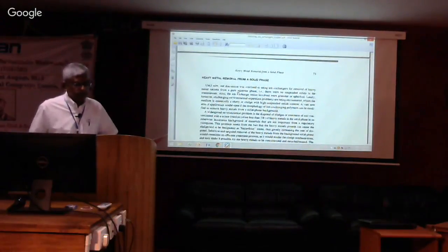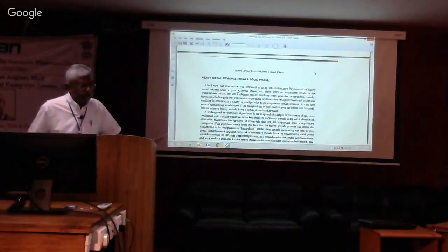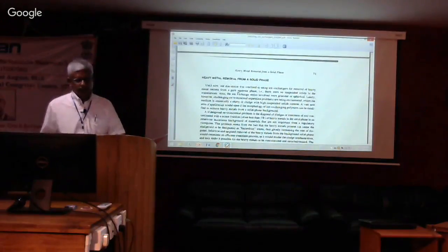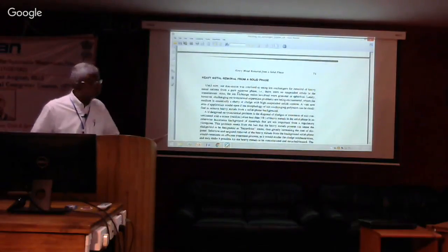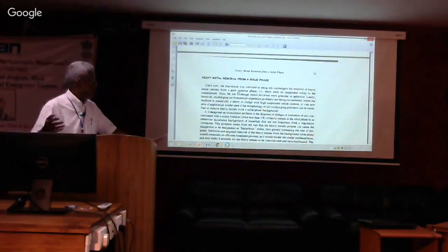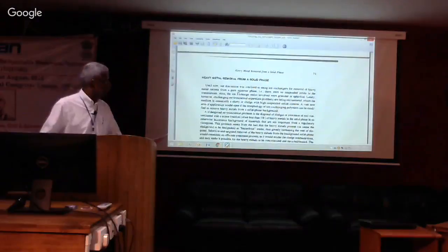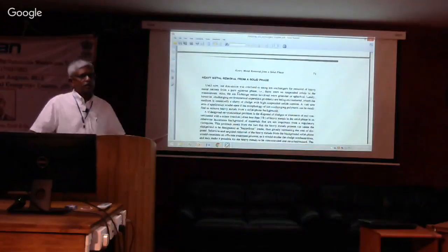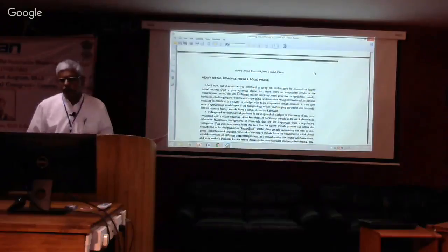to be revisited or revised, because if I'm looking at soil and if I have a soil slurry with very high suspended solids, then of course this process will not work. So what do we do? We look at a chelating exchanger or an ion exchanger, but the morphology now needs to be changed. So I would like to discuss a little bit how one can get exchangers with some different kinds of morphology. Okay. So bear with me for a moment.